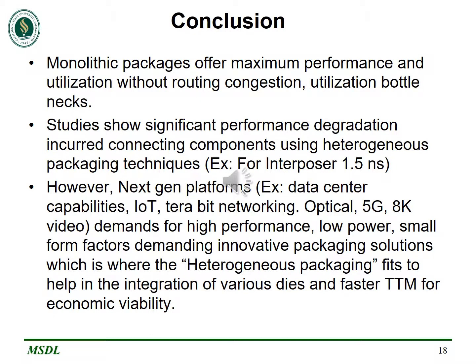In the end, it's always the monolithic package design which we need for better performance and utilization, and also for less congestion. Studies clearly show that there is a performance degradation of about 1.5 nanoseconds using interposer packaging techniques, which might be better if we use EMIB. However, the next gen platforms need heterogeneous integration for faster time to market and economic viability. Thank you.